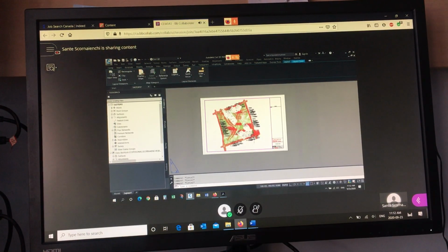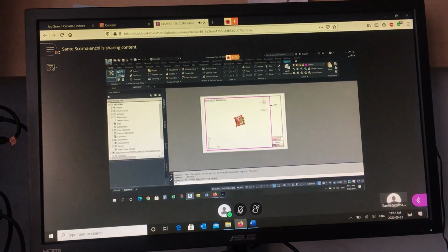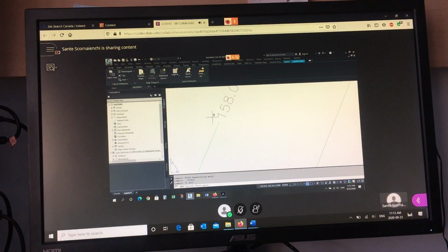Now to prevent that from happening, and notice when the object gets smaller in paper space, if I regenerate, the items would get bigger. If I zoom in, the object gets bigger, I regen, everything has to get smaller. So it's always trying to compensate. It's always trying to keep a constant text height. It's annotated. Okay? When you zoom in on here and measure in paper space, the text should be about 2 millimeters high. Oh, okay, in this case, 1.5 millimeters high.